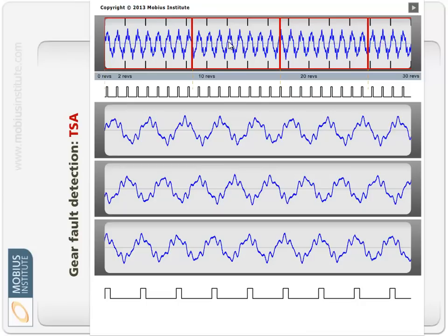it just keeps on taking chunks of the time waveform, and if I was to look at each of the time waveforms in this little time record, in this time record, in this time record, let's just call it average 1, average 2, average 3, average 4. Well, if I look at them stacked above each other, you can see that there's no commonality between them. In other words, this one goes high at the same time as this one's at the midpoint in its cycle. This one's going high here, where this one's at the midpoint, and so on.